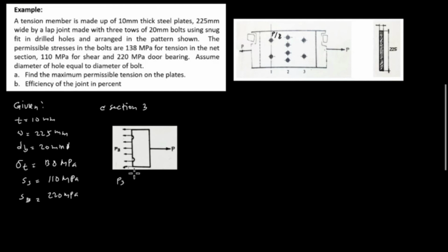We have a tearing plate, and the same concept, tensile stress multiplied by the thickness of the plate, and then the height of the plate minus, and how many bolts on the tearing plate? We have 1 2, so we multiply by 2,